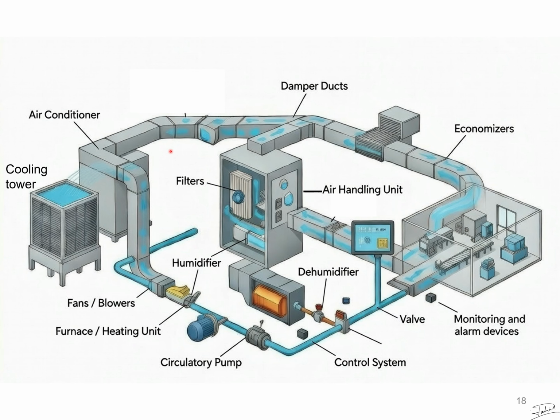So this is the overall overview of our manufacturing area, which contains an HVAC system. We can see here that this is our manufacturing area. Our manufacturing area is collecting the fresh air. So how is fresh air coming? The fresh air is coming directly from the air handling unit. So what is the function of the air handling unit? This is filtering the air. It can be outside air or it can be the manufacturing area air. Whatever the air is, the air handling unit will filter that air and supply it into our manufacturing area.